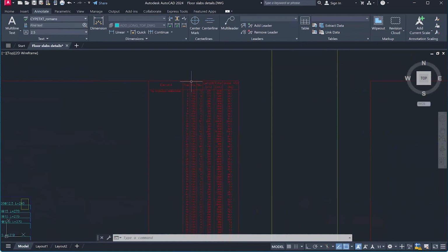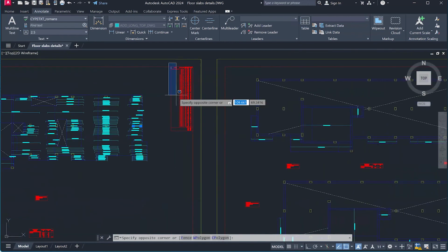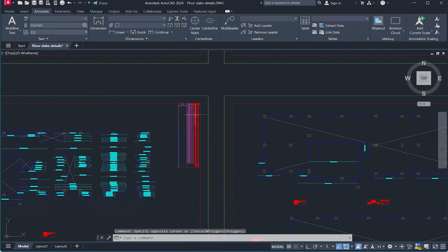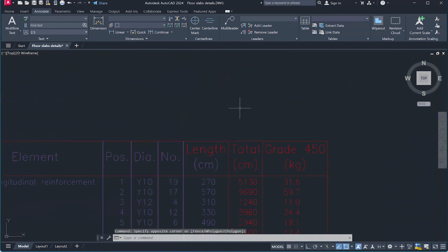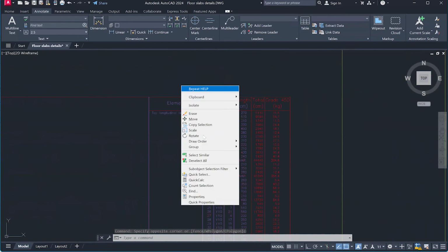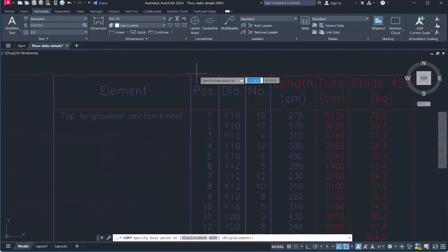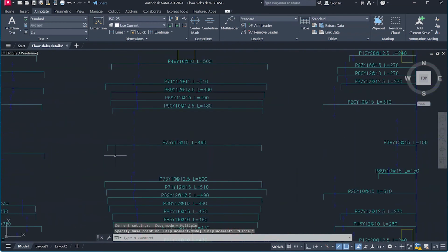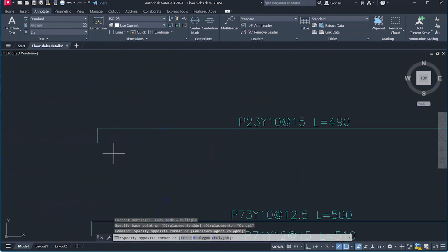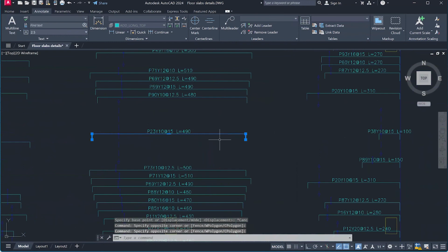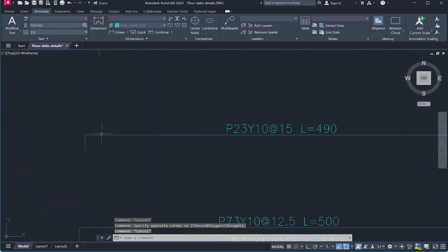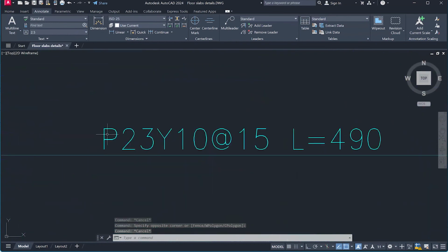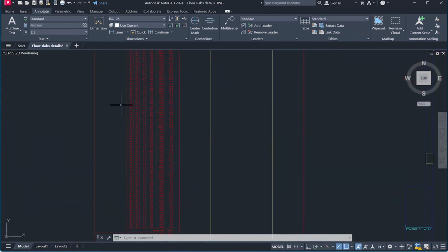All right. Then, because of the type of shape code that we have in South Africa, I would recommend to any other engineer using the software not to be limited, but to add a column whereby you're just going to assign the shape code of each bar. You just look, for example, this one here, it's a shape code 35. So what I would normally do, it's a double hook shape code 35, position 23, then I locate that position.